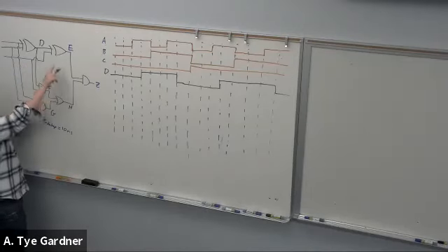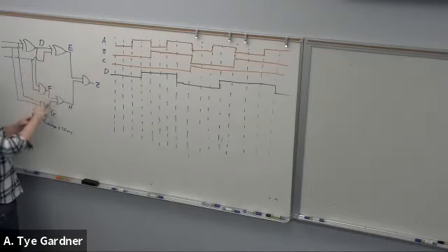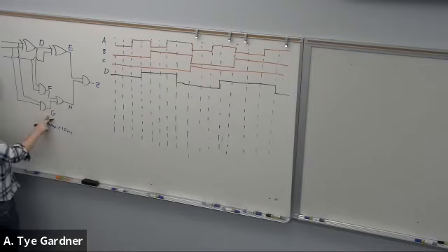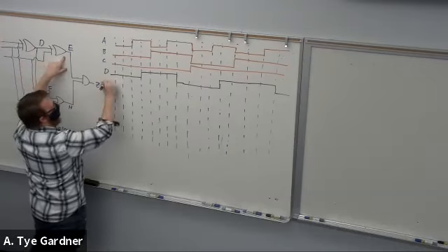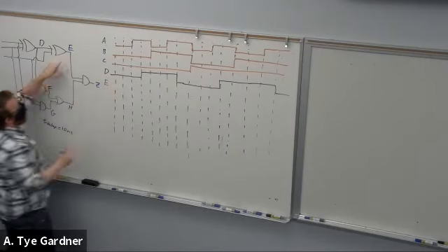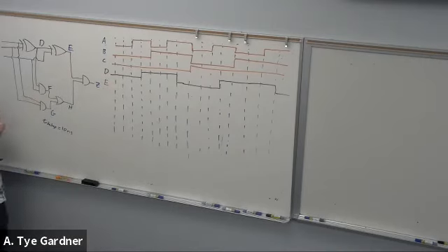E or F makes sense. So we've made D. G is pretty easy because it's, again, A and B. So maybe we'll do G next, but I'll just move on alphabetically for E. So E is going to be another XOR operation, but I only have to worry about if D and C are different. I don't have to worry about A and B anymore because I've done D.